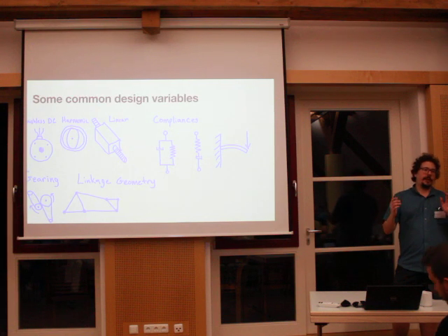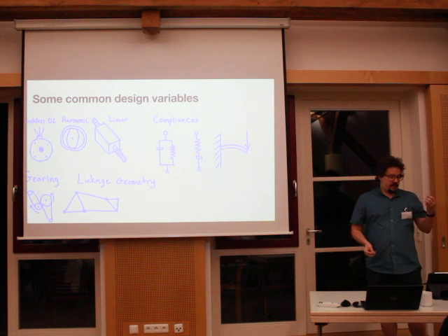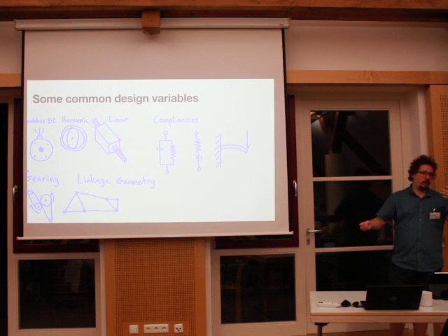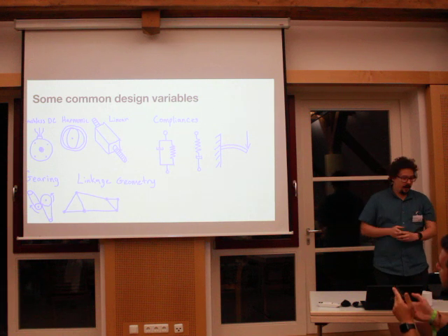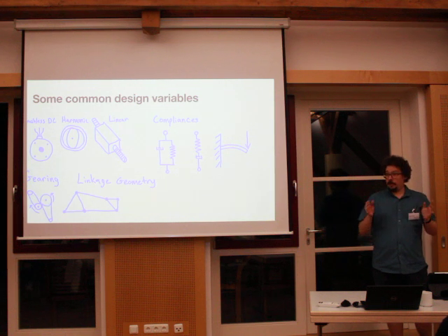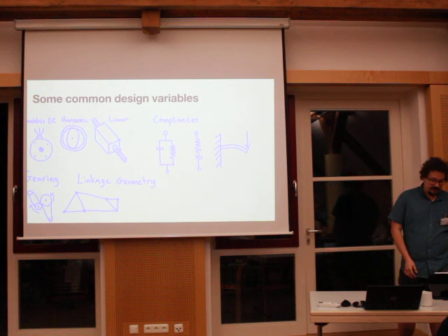When we're designing legged robots or robotic prostheses, there's a lot of things that we have to weigh. We have to make choices like, what type of motor am I going to use? What size is it going to be? Is it a brushless DC? Is it a harmonic motor? Am I going to use linear ball screw type things? Also, over the years, we've seen a lot of talks where compliance plays a really big role in the design of robots, whether that is for storing and returning energy, or protecting the motors from impacts in series elastic elements. And two more really important ones are, what's the gearing that I'm going to use? How do we build the transmission of our robot? How do we optimize the geometry of our linkages and the transmission and things like this?